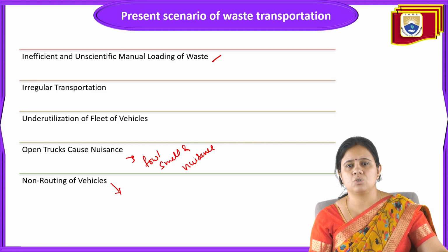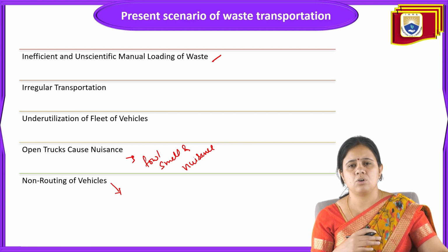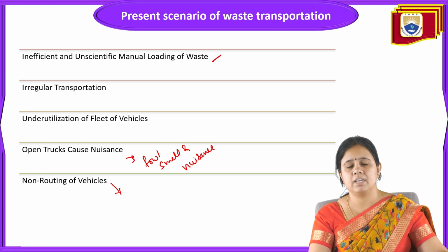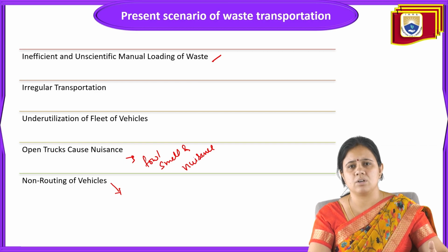Transportation should not create any kind of nuisance. It should not pass through heavy traffic areas, or if it does, the waste collection should be done in the morning only. Only covered vehicles should be used, so that no litter is spread on the street. Vehicles should also be filled properly, with no space left, so that the work is efficient and cost effective.